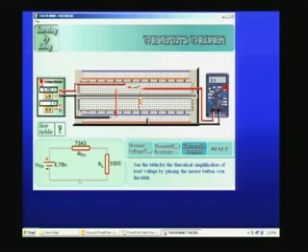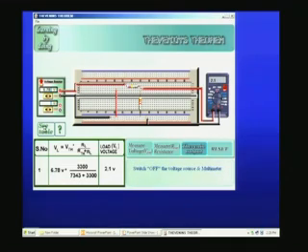Immediately the voltage comes out to be 6.78, which is the Thevenin's voltage we have calculated, and therefore I set this for 6.78, and I just measure the output voltage across the load to be 2.1 volt, which is what we calculated in the previous example. You can see that the output voltage is also shown in this table. Easily you can see that it is about 2.1 volt.